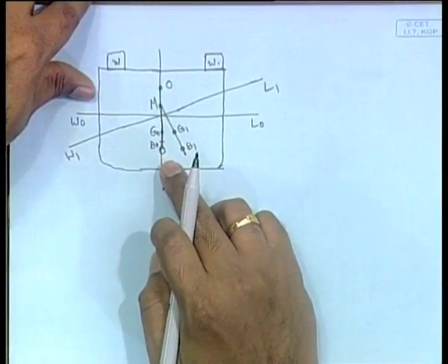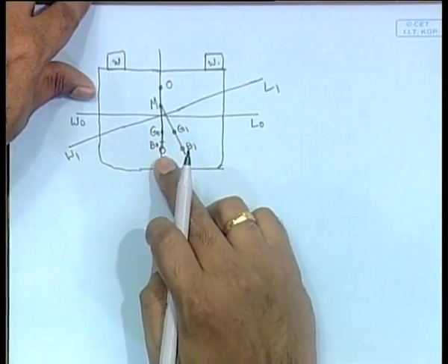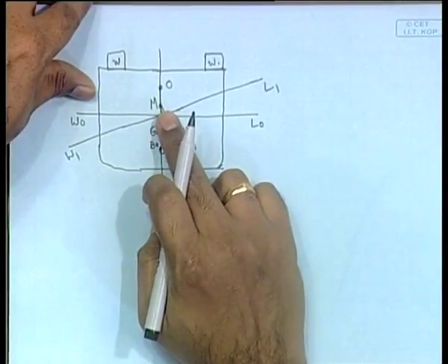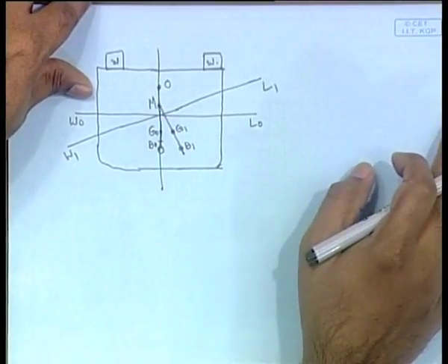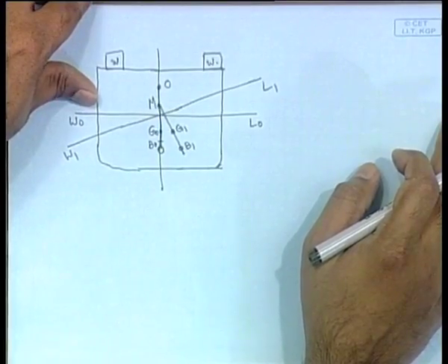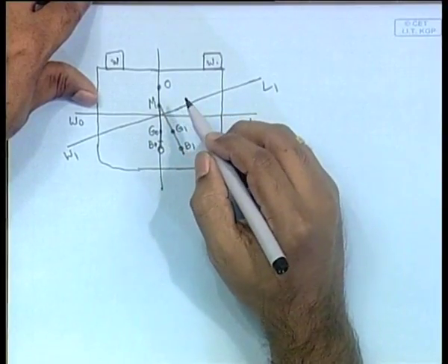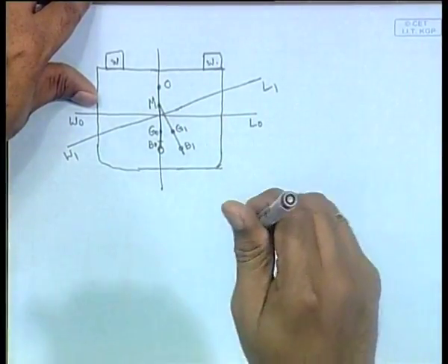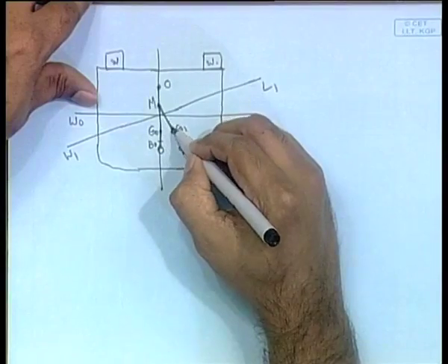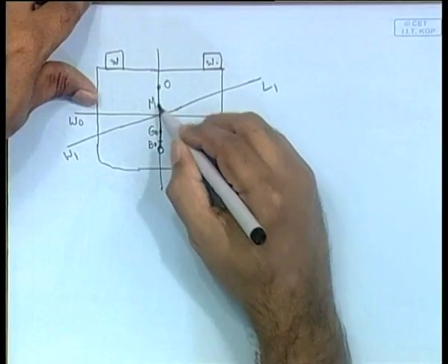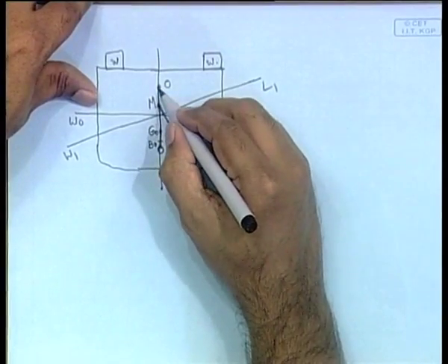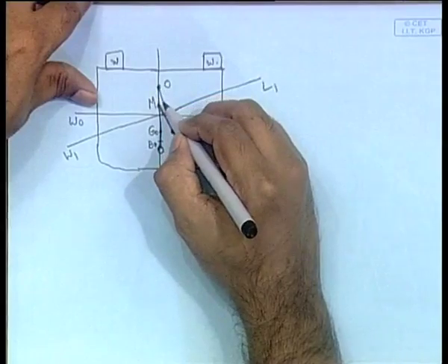Now the weight is moved to the right, as a result of which the ship sinks on that side, and the center of gravity shifts to G1, the center of buoyancy shifts to B1, and you have the M, as you have seen, the metacenter. Now, how will the pendulum look? The pendulum will still hang vertically in the new position. So it will be hanging like this. Okay. This is the vertical. From O it will be hanging vertical.